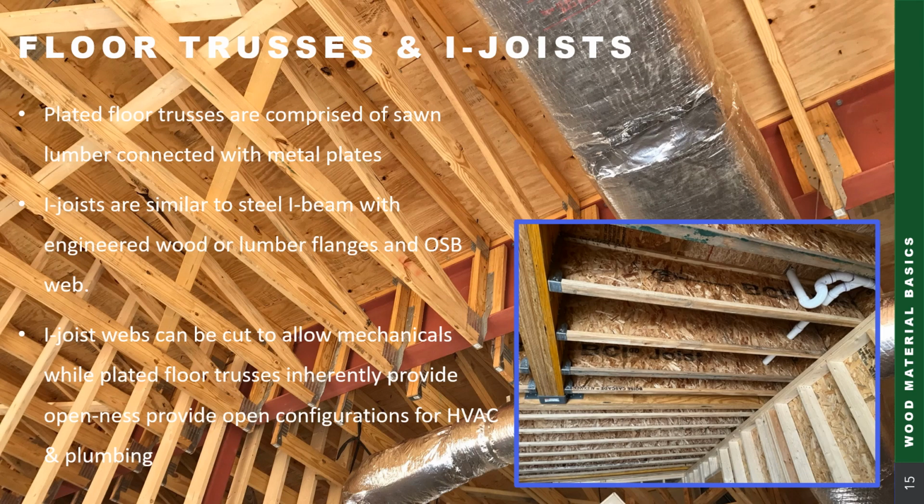Well, the most common application for trusses is in the roof. Trusses may also occur in floor systems. So this gives you an example. This would be a plated floor truss in a floor system. You can see it's supported by a steel beam. These do have metal plate connections. There's a good example right there of a metal plate connection.